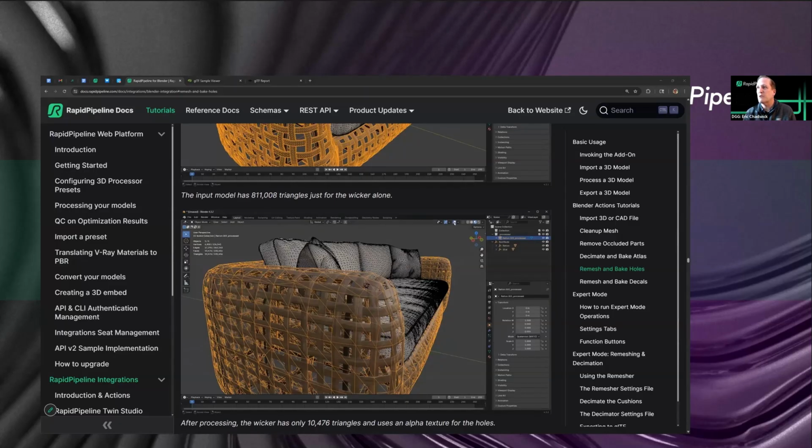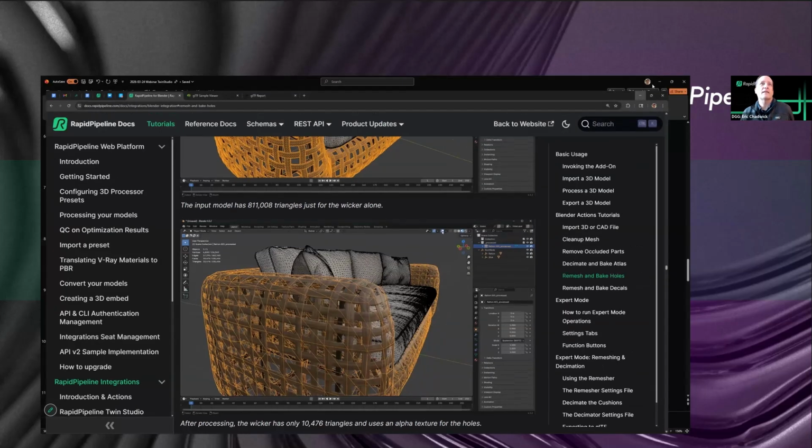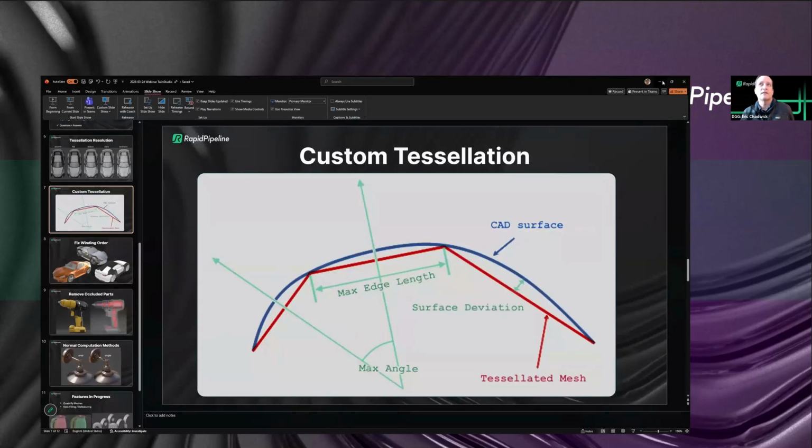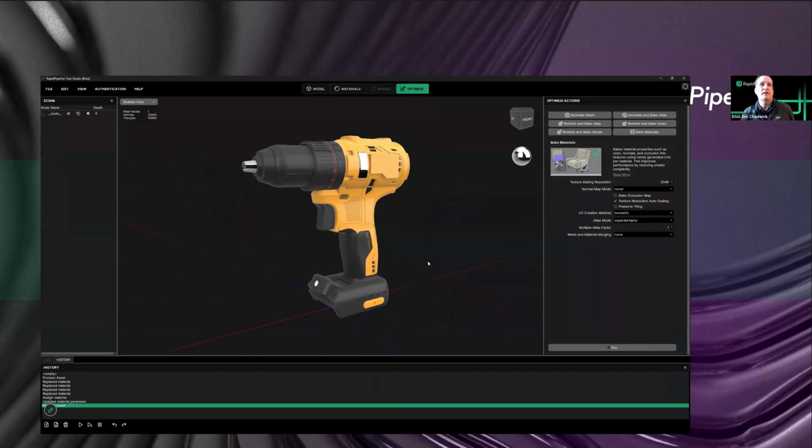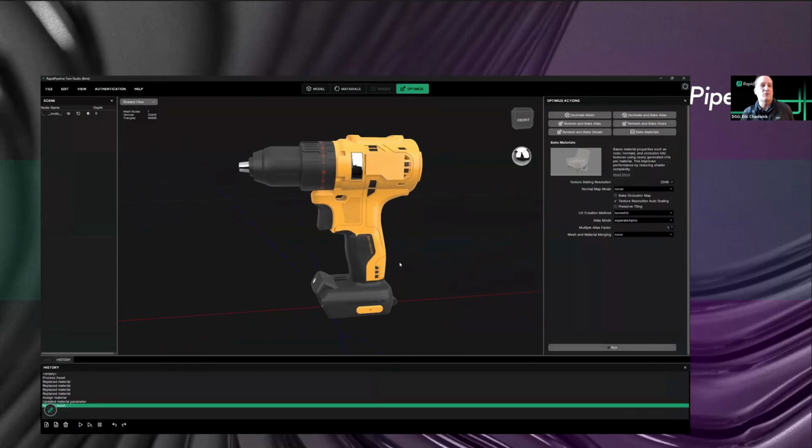We got another one: purchased models from various online stores often have messed up texture mapping with broken pathways and poorly organized files. Can the cleanup and reconciliation of this be automated? Yeah, so we can support some of that, right? If it's missing textures, there's not that much we can do with that data, other than, if it is an ASCII-based file, like a USDA file or a glTF file, you can go in and find and replace those broken paths.